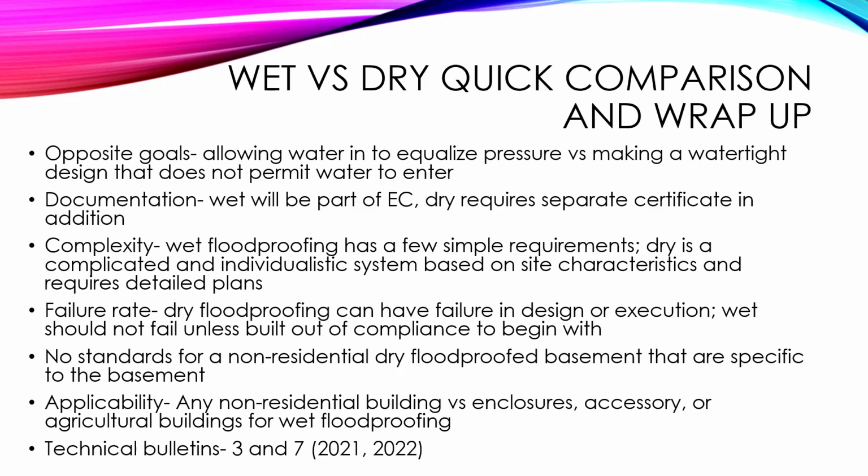Failure rate, wet should not fail unless it's built out of compliance or just a massive flood is the cause of that. Dry floodproofing, obviously there's a high failure rate if you have one flaw in that design. So there's no standards for a non-residential dry floodproof basement that are specific to the basement.